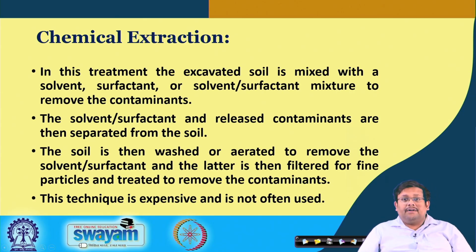The next method for ex situ soil treatment is chemical extraction. In this treatment, the excavated soil is mixed with a solvent, surfactant, or solvent-surfactant mixture to remove the contaminants. The solvent or surfactant and released contaminants are then separated from the soil, and the soil is washed or aerated to remove the solvent and surfactant. The latter is then filtered for particles and treated to remove the contaminants. This technique is expensive and not very often used.